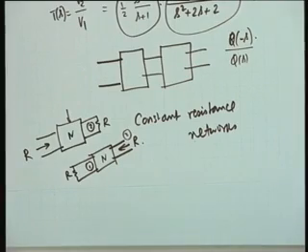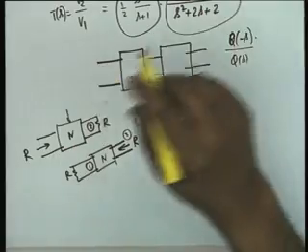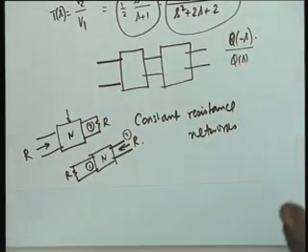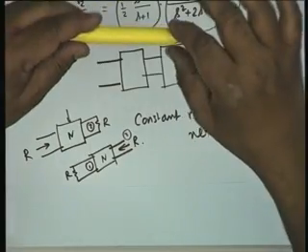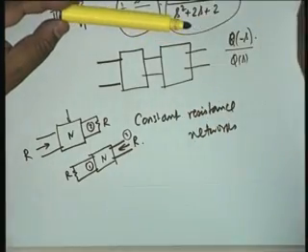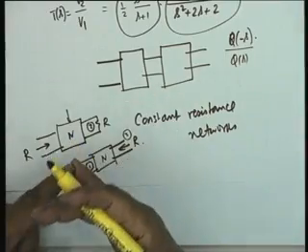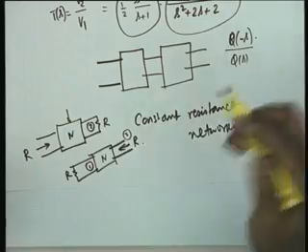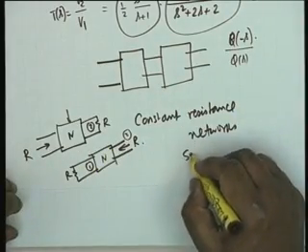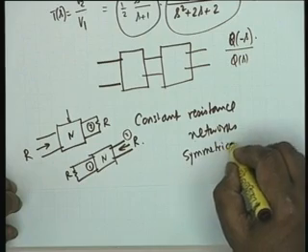That is correct. It is symmetrical. No, bilateral, let's clear this. Do not make this mistake. Bilateral refers to a two-terminal element, that is, current passes equally well in both directions. On the other hand, if a network contains only bilateral elements, then it is called reciprocal. Reciprocity is understood. We assume that all networks that we are considering are passive, linear, time invariant and reciprocal. All right. Now this gives the character that constant resistance networks must be symmetrical.